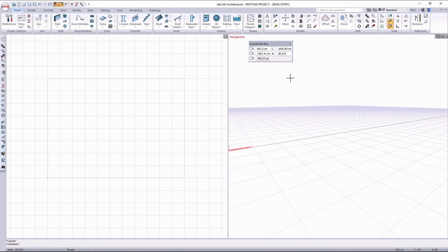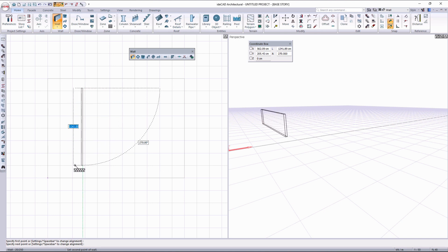You can adjust snap options like Snap to Grid, Snap to Nodes, and Advanced Snap as you like. You can exit commands using the Escape key, re-enter the previous command by clicking the mouse wheel, and use the Shift key for alignment.